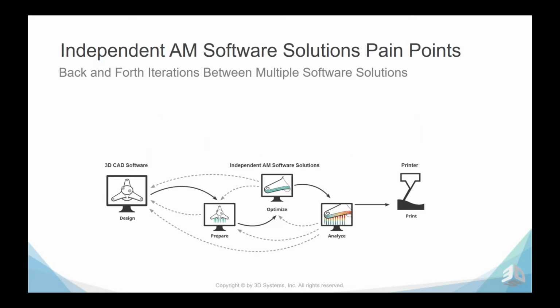The very basic drawback is that in many cases, each software is using a different environment, which means that when you move from one function to another, you also need to change formats and use file conversions. So there is also a good potential for errors that you will have to spend a lot of time to fix. CAD integrity, for example, is downgraded with the conversion of BREP to mesh when you move from one solution to another or from one function to another.